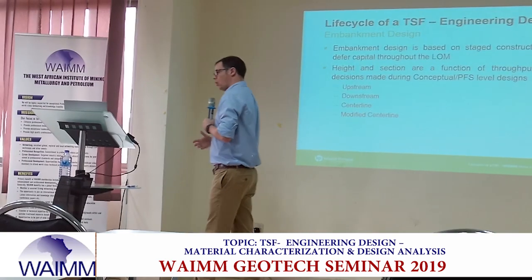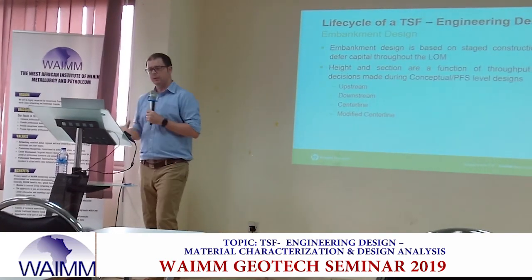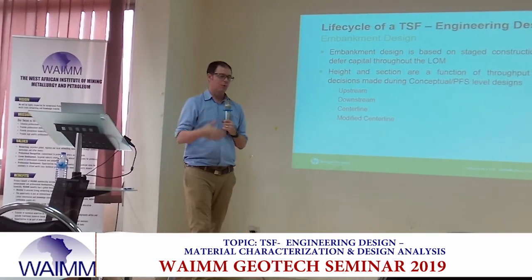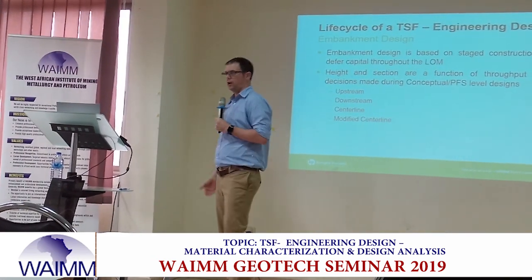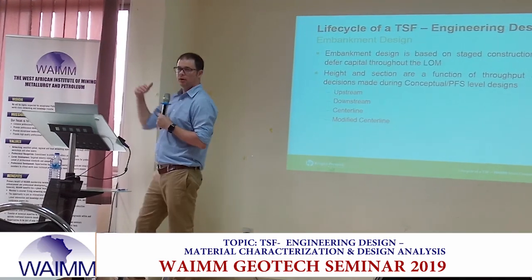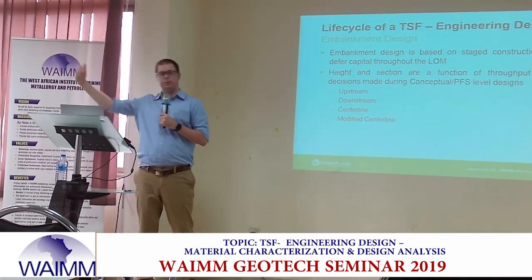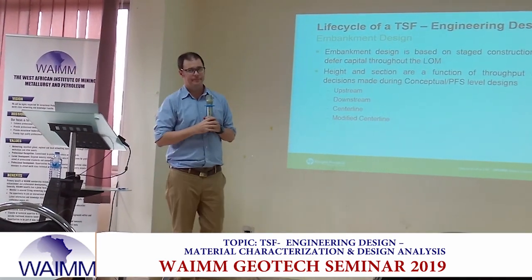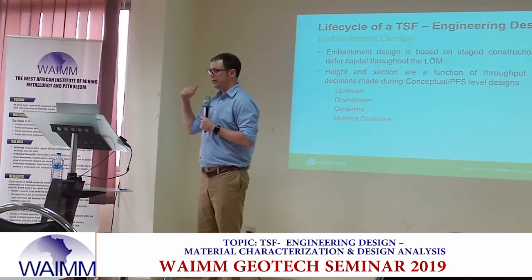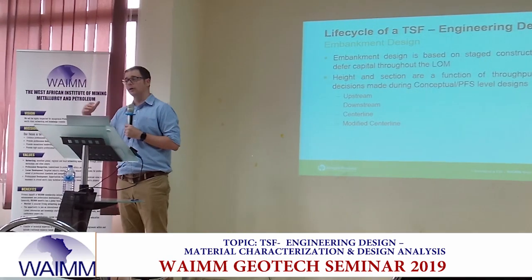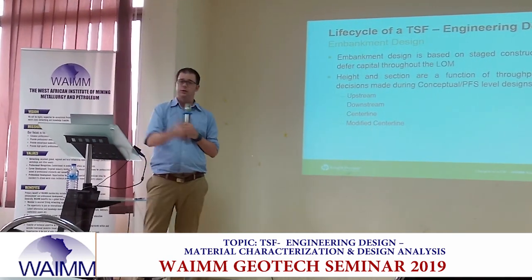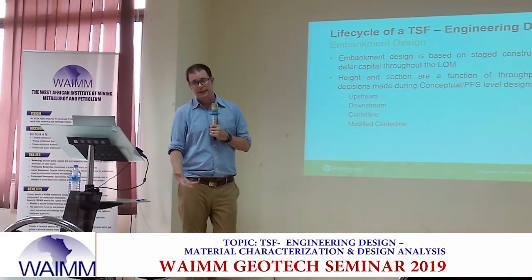A tailings dam, we don't need the whole thing at once. So we typically build it in stages. And what that does is it defers time, but it also defers construction costs. If I can spend $1 million tomorrow, I'd rather spend it tomorrow than today. So we need to look at our stage development throughout our life of mine. Do we want to build every year? Do we want to build every 2 years, every 5 years?